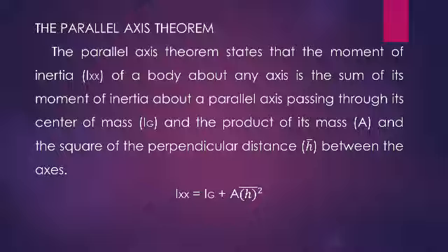Next one is we are going to know about the product of inertia. We already studied about the product of inertia. It is represented by Ixy. Ixy is equal to integral over A of xy into dA. Then the next one is principal moment of inertia. Principal moment of inertia is represented by I maximum or IUU, comma, I minimum or IVV.